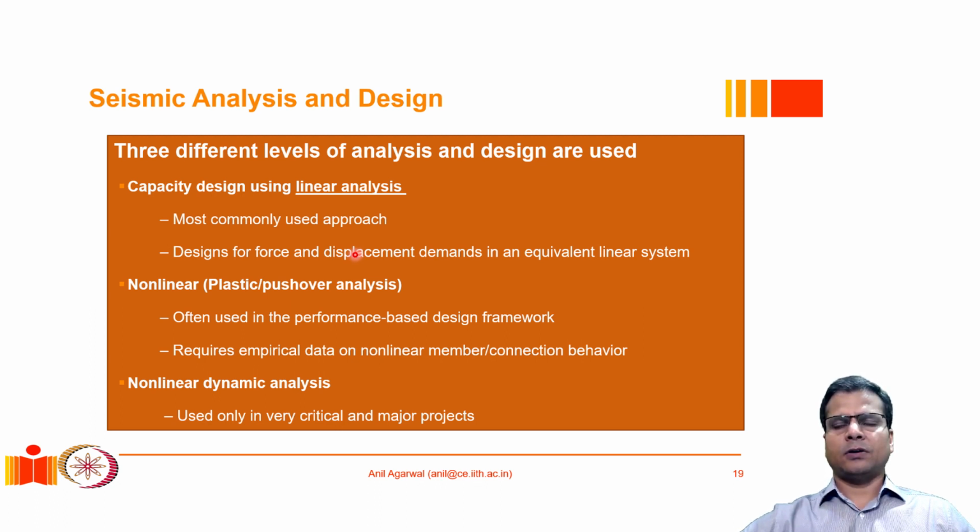So there is a design philosophy known as performance-based design, wherein the idea is that the structure should be designed to perform in a certain way under a certain magnitude earthquake. That kind of objective cannot be fulfilled with this approach. The approach that can be utilized to fulfill the objective of performance-based design would require some level of nonlinear analysis. The commonly used method in performance-based design is known as the nonlinear pushover type of analysis.